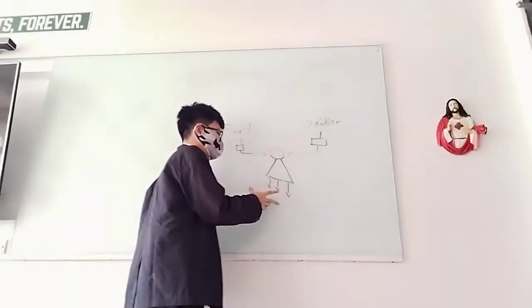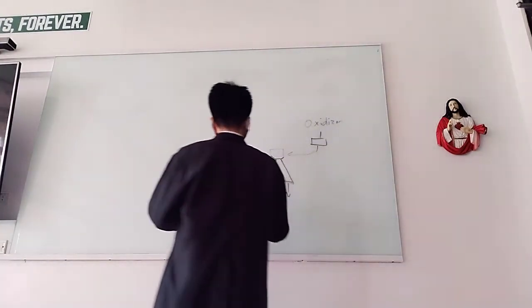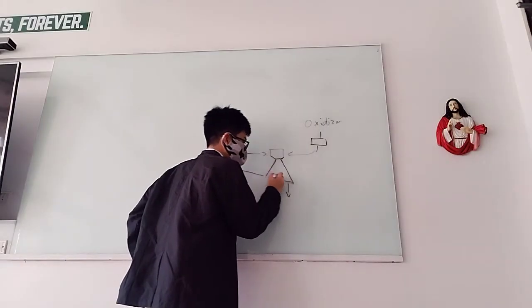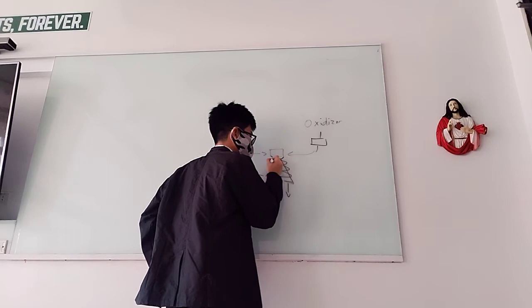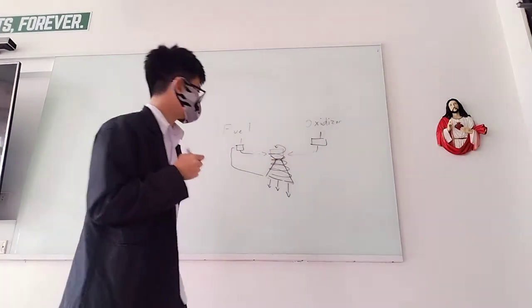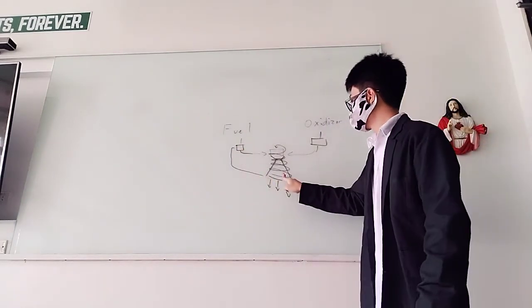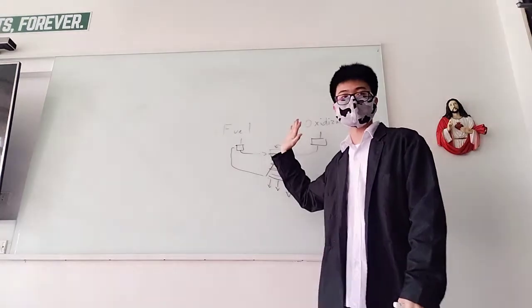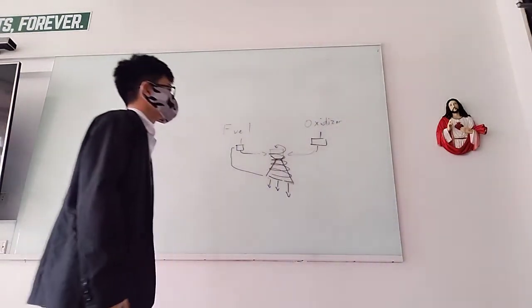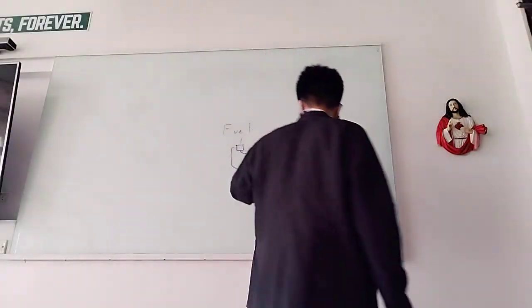Okay, so regenerative cooling is where you have the fuel, right? And part of the fuel that comes from the pump is run throughout the engine and then fed back into the engine. So you have part of your fuel go here and then around the nozzle or up the nozzle so that it cools the engine. And then you feed it back into the engine. Or you can use the oxidizer, but mostly the fuel is subcooled, and then you just inject it there.